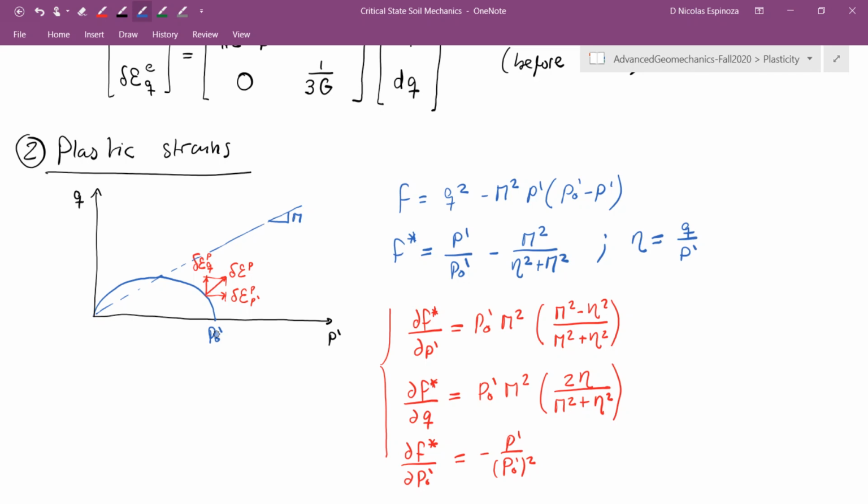So because the rock saw a higher stress in the past, if you apply a new stress which is not as high as that stress in the past, the rock might behave more or less elastically, and it will come back to the so-called virgin compression line once you reach that pre-consolidation stress, or the largest stress that the rock has seen in its history. That's why it's called a pre-consolidation stress. All right, so this is a very important parameter then in the modified Cam-Clay model.